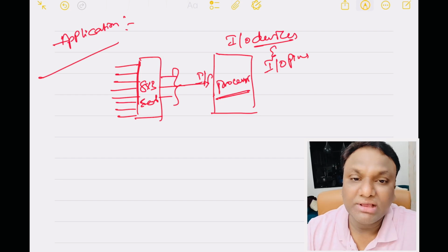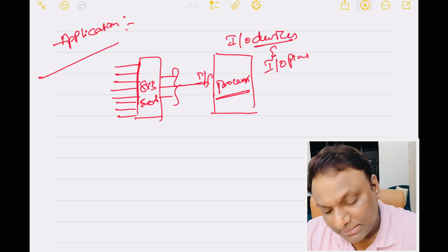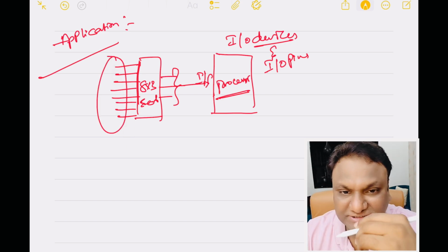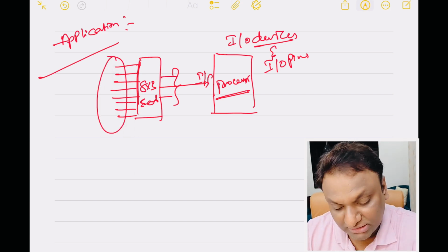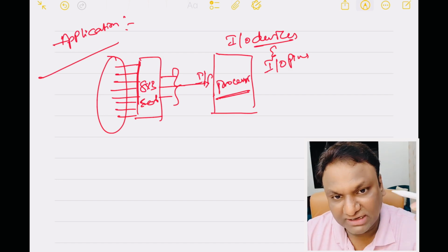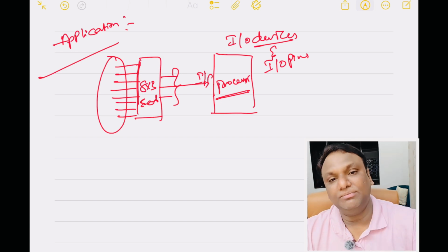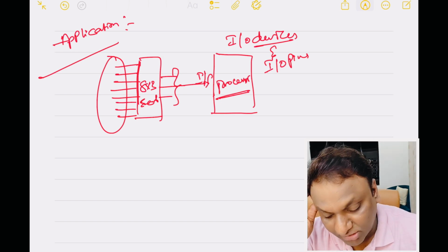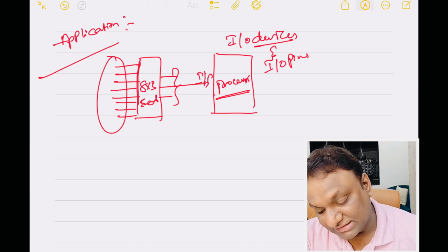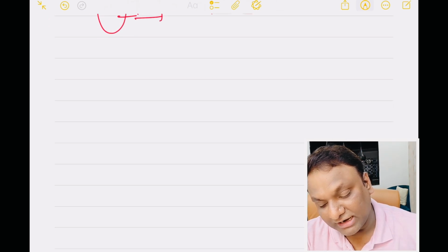These can be used as the IO pins to the processor. So for a large number of inputs, I will be getting the output of an encoder, and that can be directly driven to the processor with 3 inputs. So I am saving the number of input pins here. This is the application of the encoder and the design.